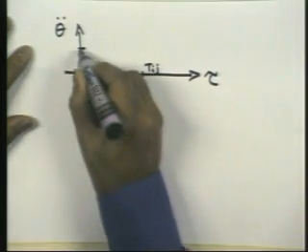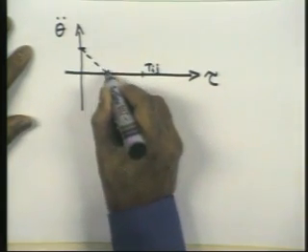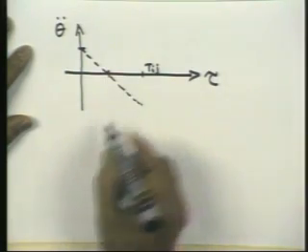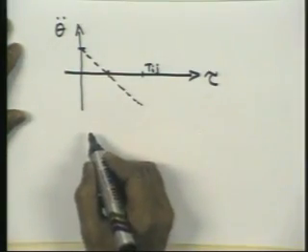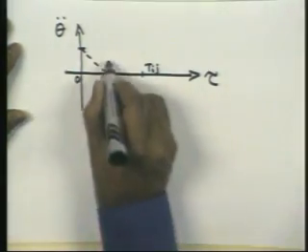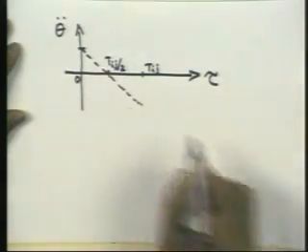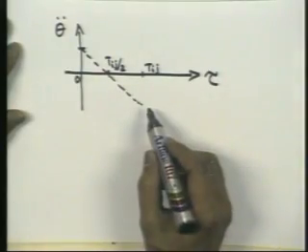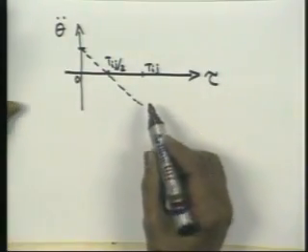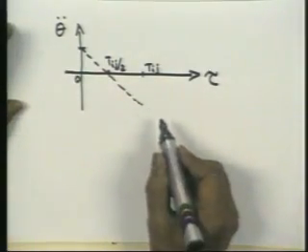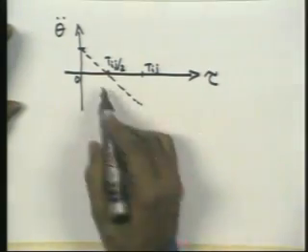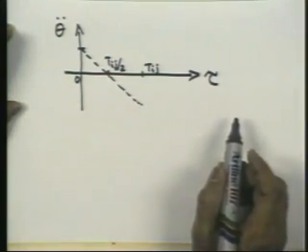Over Tij, the accelerations will actually move like this. Okay, accelerations will be linear, crossing zero at Tij upon 2, the halfway point, where the peak velocity is, and then there will be a deceleration phase after that. So, you will have this type of acceleration profile.